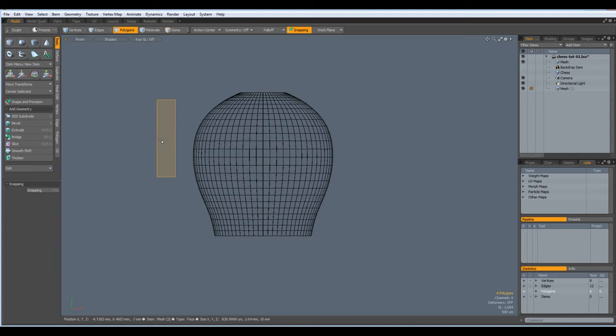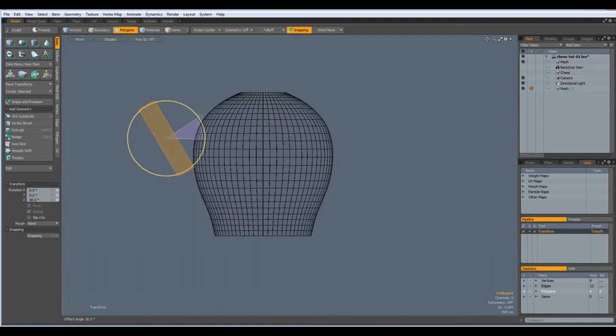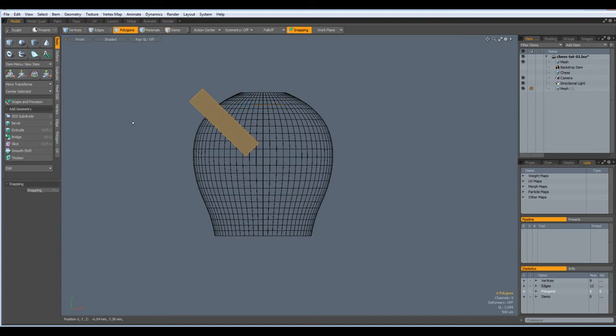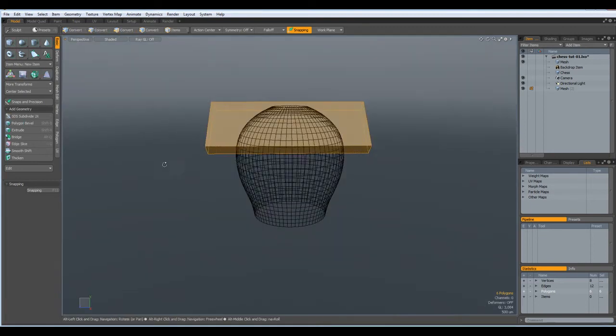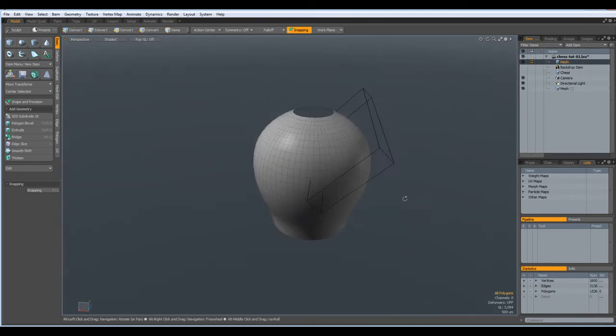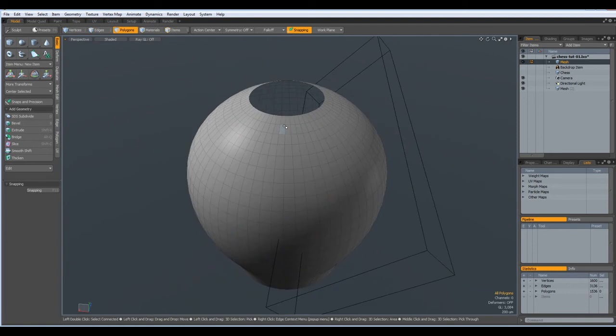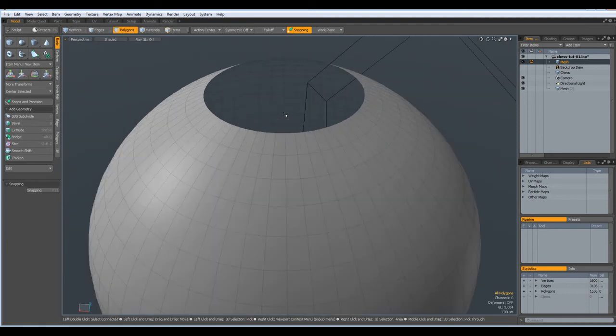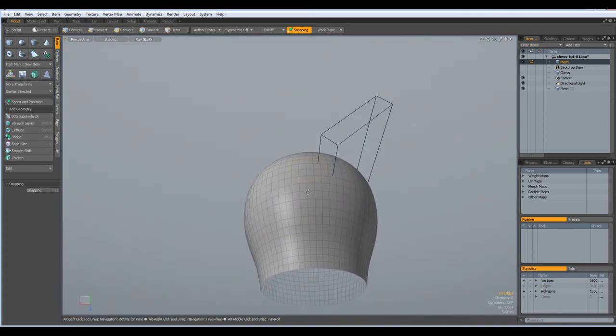and then I rotate this by Control, rotated 45 degrees, W key, and bring this to about here. It doesn't really matter. Okay, now let's see how this looks in perspective. Good. Let's go to the other mesh and close this mesh so we hopefully can do a Boolean operation.